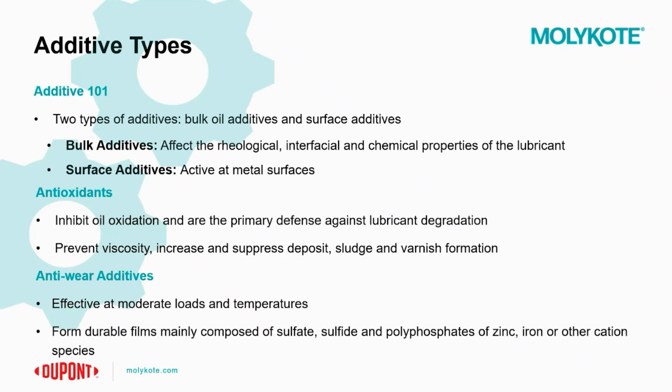And in that case, when you have a grease or a lubricant in that kind of system, it will start to undergo oxidation. The lubricant itself will begin to oxidize. And when that happens, the base oil itself will not be able to prevent against the effects of oil oxidation. So ultimately, what will happen is that oxidation will produce polymers that overall increase the viscosity of the grease or of the lubricant, and eventually accelerate the wear and lead to varnish on the surface that you're applying the lubricant to.